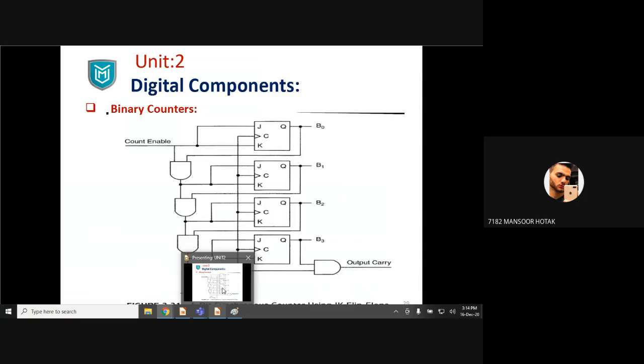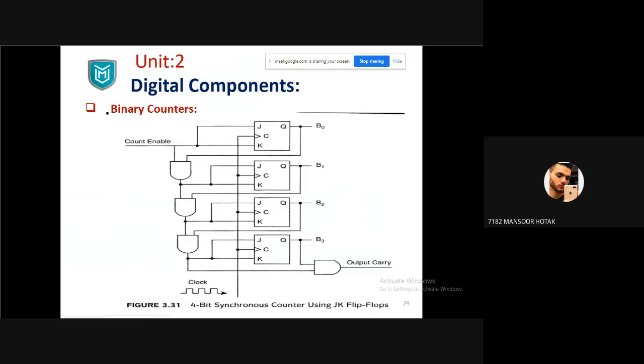So there, I also see an enable, which was in that multiplexer. Enable switch is there, common enable switch. Okay. Then there are 4 registers. You use 4 flip flops, right? Yes, for D flip flops. But yes, there is a difference. We use 4 flip flops. In that we use D flip flop, but here for the counting purpose, I use JK flip flop. See, it is up to the application. What type of application do you have? If you want good results for counting, then JK is better. Okay. So instead of this D, we are using JK flip flop.